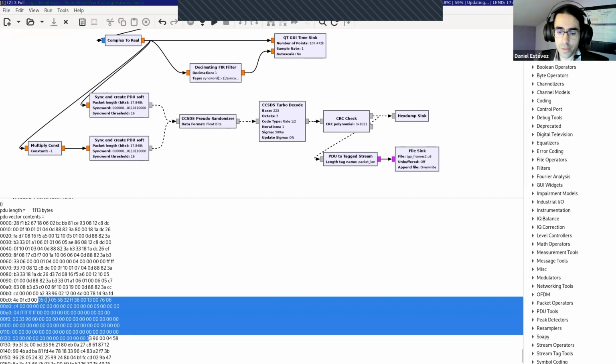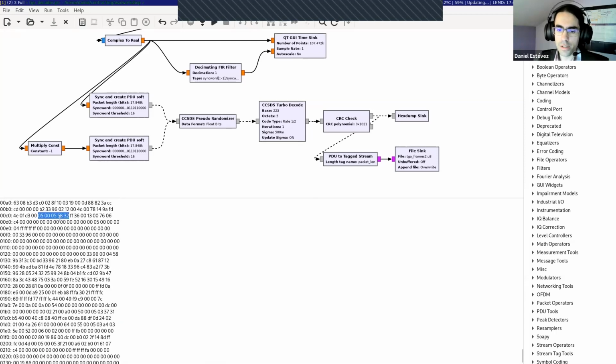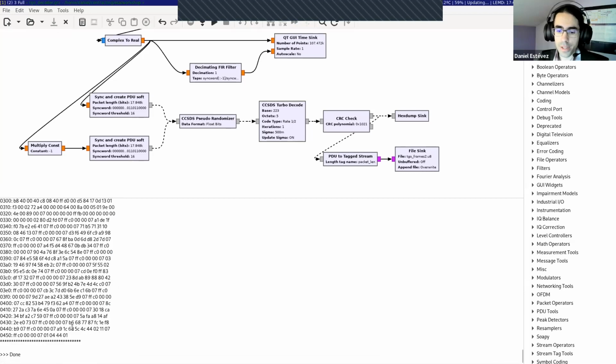Let's pretend it's here. And then in the space packet header, in the first 5 bytes of the space packet, you have the length. So let's pretend it's this. Then you would say, oh, okay, this is the length of the space packet. So it begins here, of course, and it extends up to here, and it ends maybe there. So the next thing is the next space packet, and you continue in this way. And when you run out of data, you move on to the next frame. So that's how you recover the space packets. And that's how people have done it.